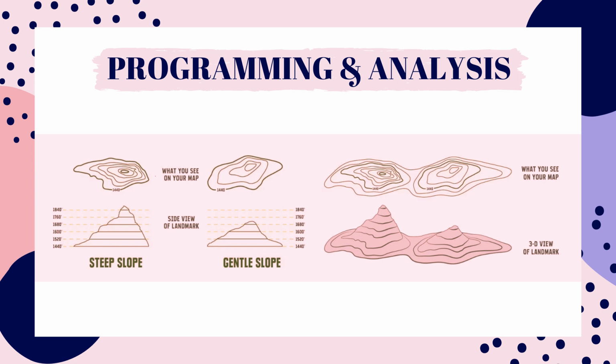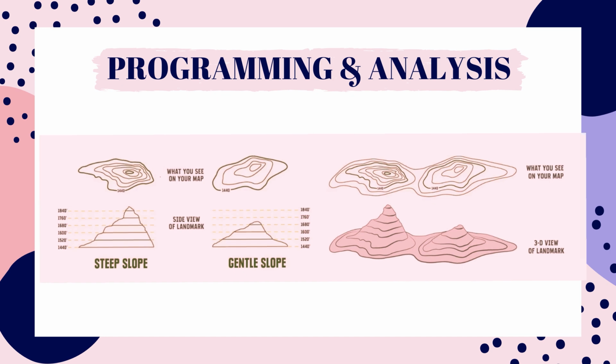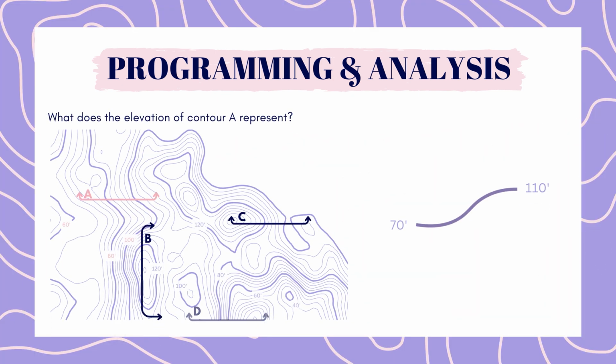When they are closely spaced together, the slope is steep. When the contour lines are more evenly spaced, then the slope is gentle. Each ring represents a different height above mean sea level, or a local reference point. In this question, our darker lines represent 20-foot differences in height, and the thinner lines are 5-foot differences. So A starts approximately at 70 feet and ends at 110 feet.